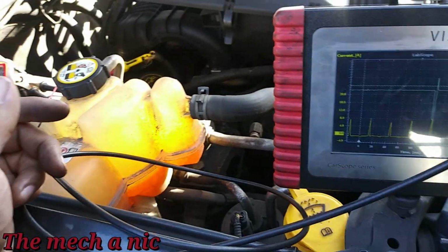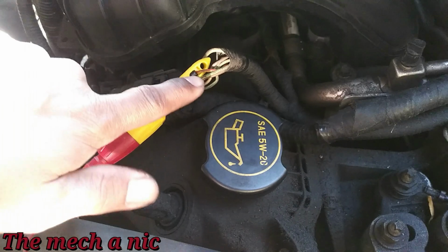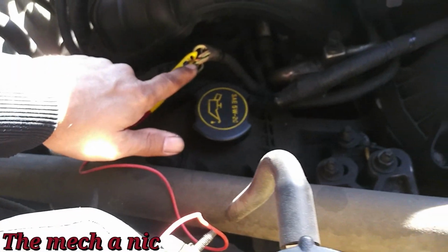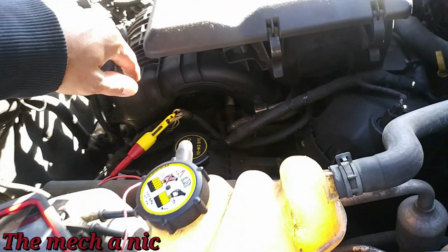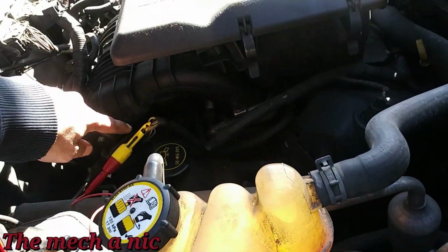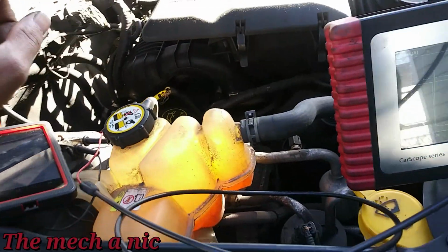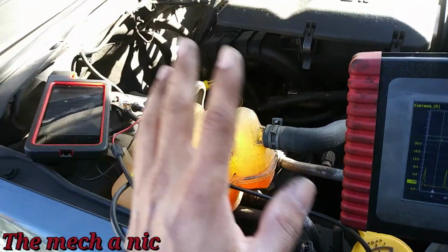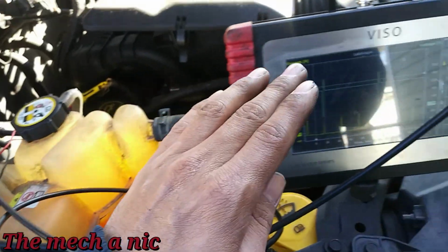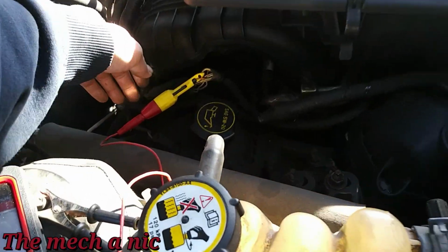for that fuel injector. Now I went through all of them, and it turns out it's actually the wire that's yellow with the red stripe for fuel injector number 4. And I was using a pin to back probe all of them, but when I got to injector number 4, I must have put my back probe in that thing like a good 30-40 times, and I could not get it to show up on the scope here. So I had no choice but to use a piercing probe.